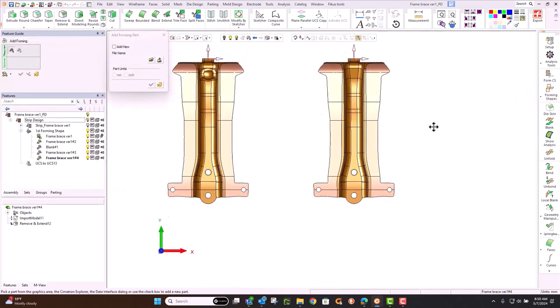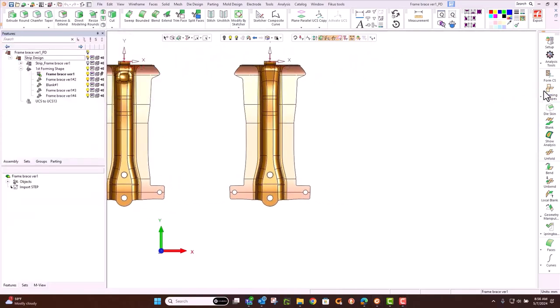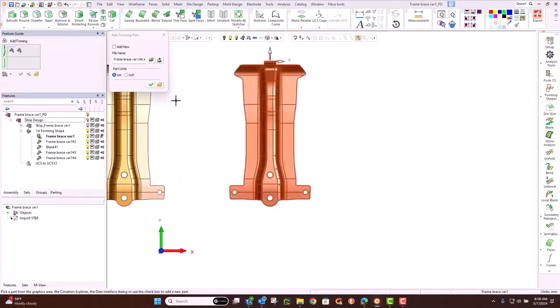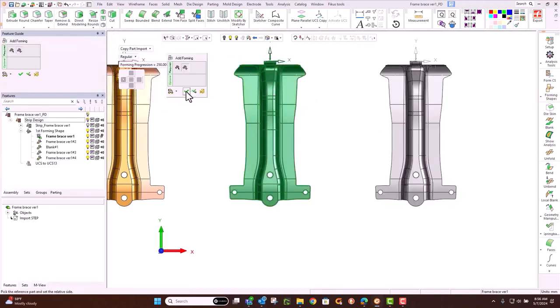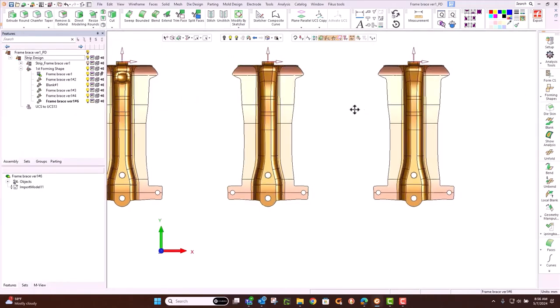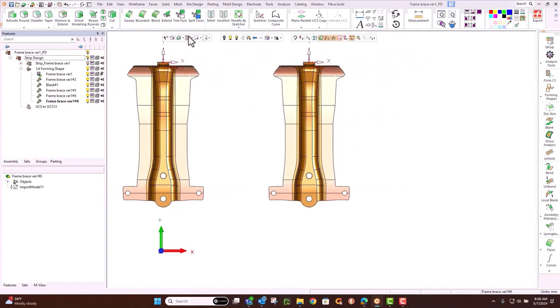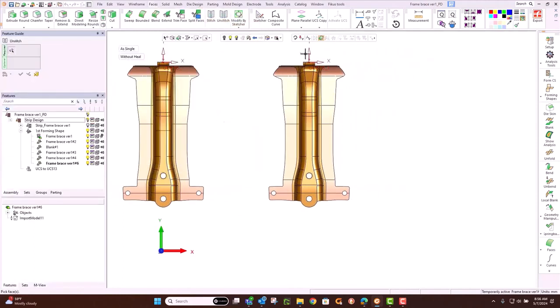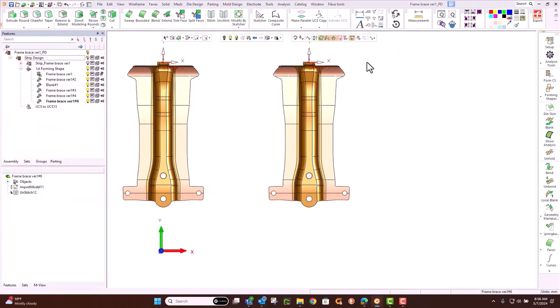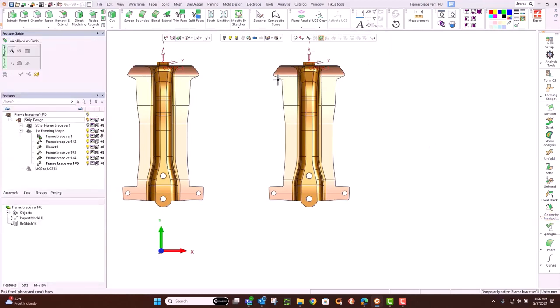Let's work to the inside of that groove. We want to develop the left and right hand sides again. So basically, I'm going to keep that tab where I know I would connect my carrier. Here I'm going to select right down the center and say this is the area that I want to develop to. We'll pick the left side again and now develop it out like that.